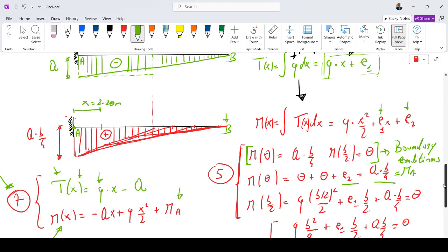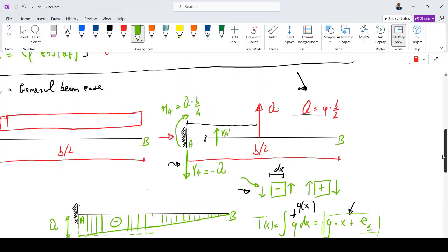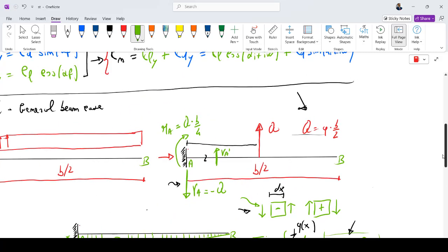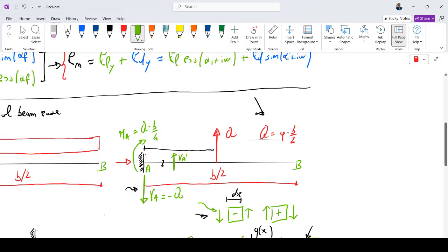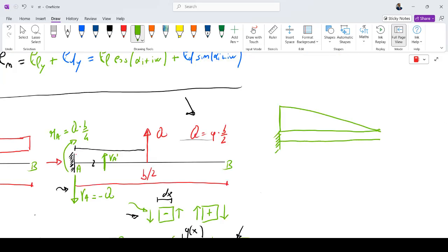You can see, if I have a linear distribution of the loads, something like this, that is quite similar to the distribution along a real wing. In this case, the wing can be expressed as having a sharp tip. It's possible, but this is a taper ratio lambda, c tip over c root, equal to 0. So a similar distribution of load is this.